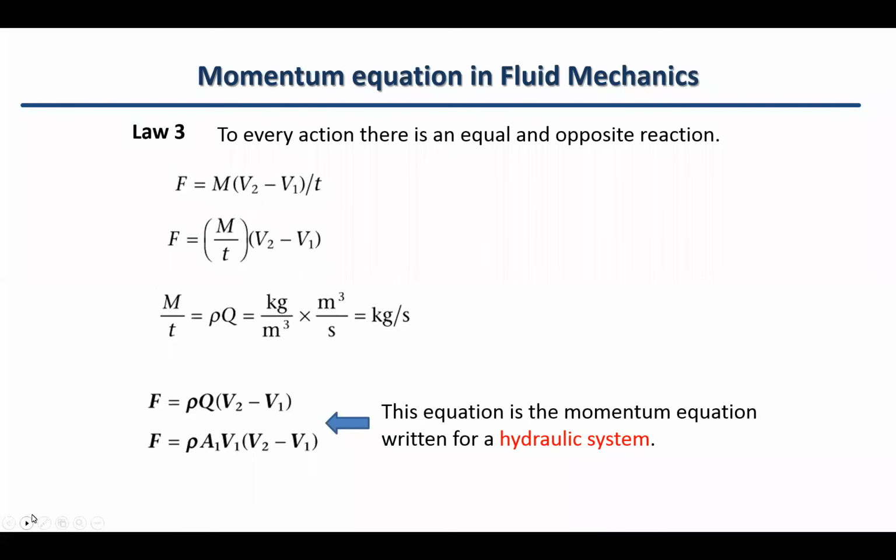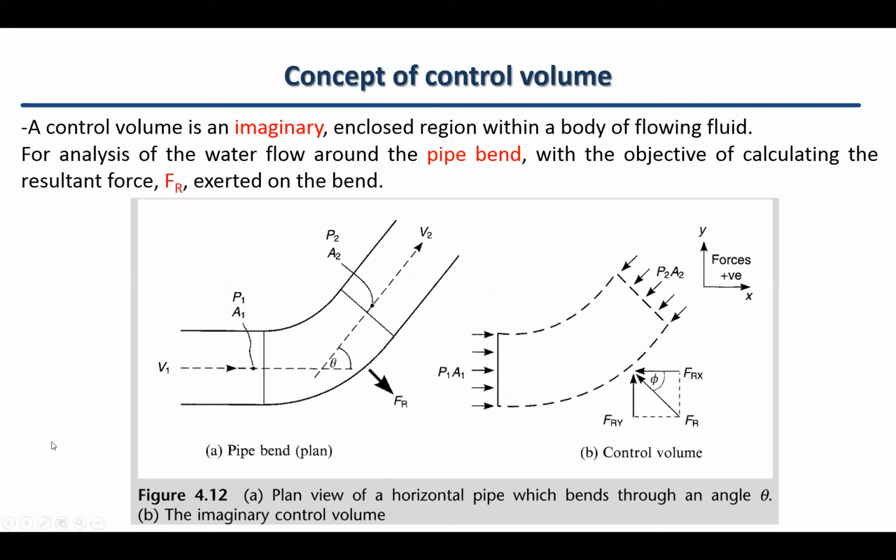So let's look at more concepts on that, and some applications of this concept. Before going to the applications, I'm going to give you an example of a bending pipe. Imagine that when you are analyzing or designing a pipeline system, the pipe has to bend, for example, to change the direction. That's fine. However, there's a problem with that. In a piping system, the water has momentum and pushes on the pipe. Once it has to change direction, it pushes on the pipe and pushes to the external side.